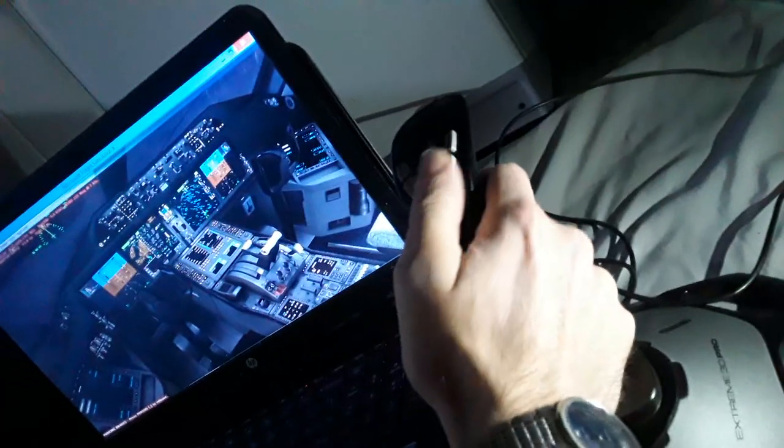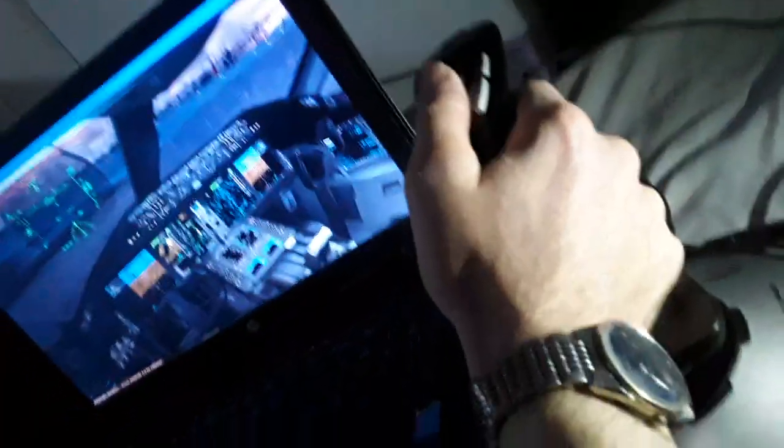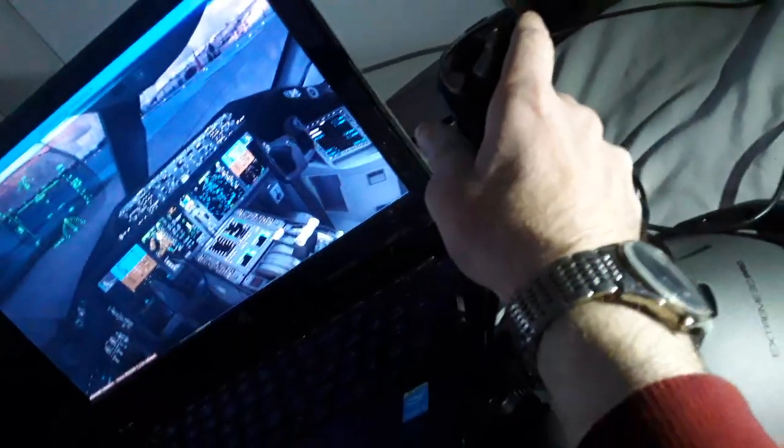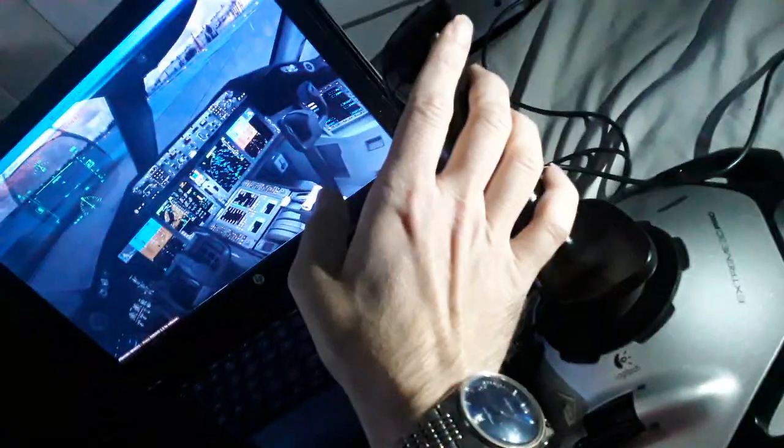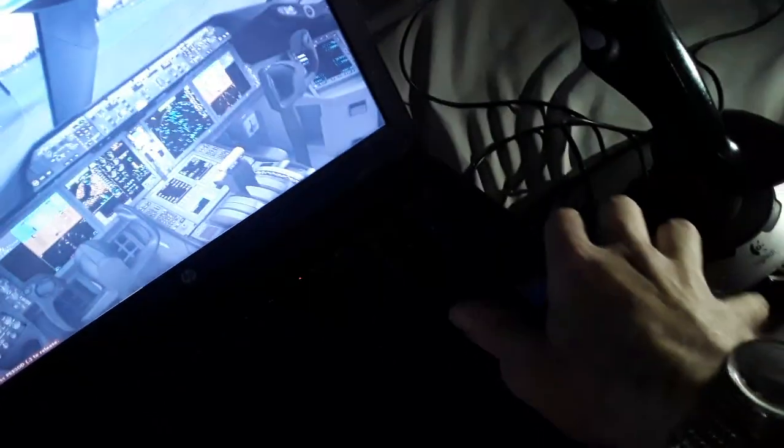Also we have the horizontal trim stabilizer that I told you here. This switch is mapped here for trimming the horizontal tail up and down to balance the aircraft and relieve the air pressure in flight. So you can see also the thrust levers over here. You can move the thrust levers forward and aft using the control of the thrust over here.